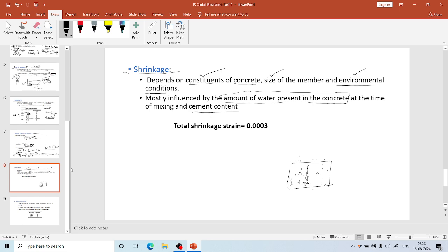One thing we have to see is the types of cement. OPC, we saw 53 grade OPC. In this, shrinkage will be more than in 33 grade cement. Normally in concrete also, if we add more cement content to obtain higher strength, because of high heat of hydration, M30 will have more shrinkage than M20 grade concrete.